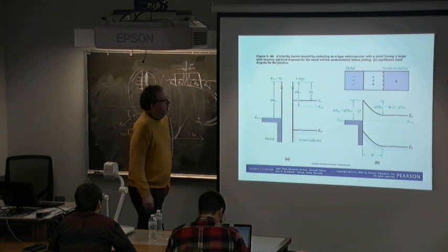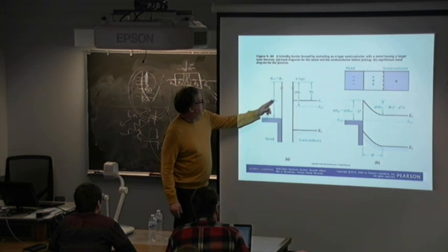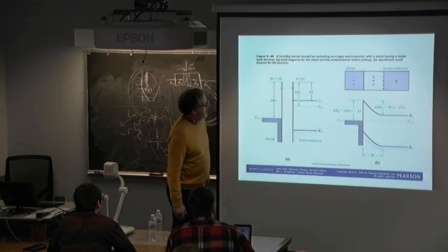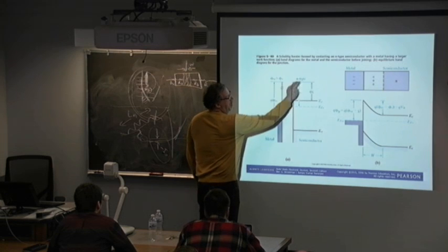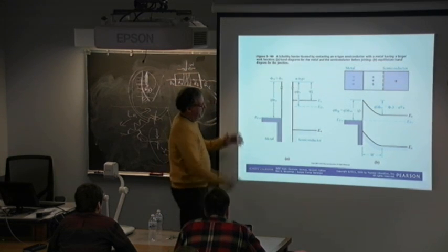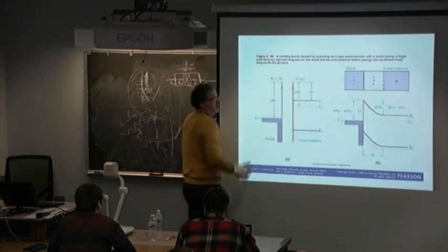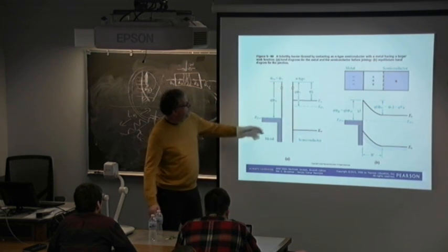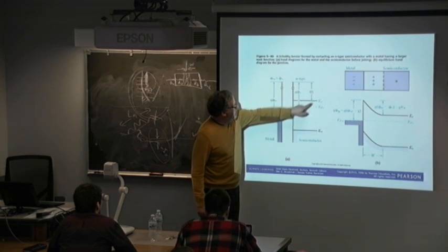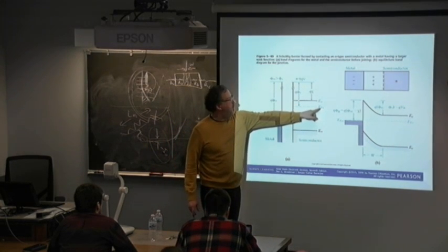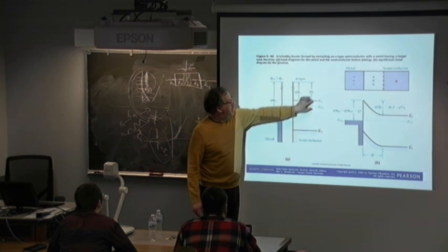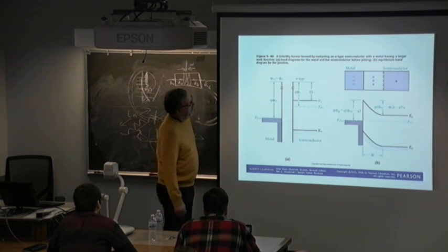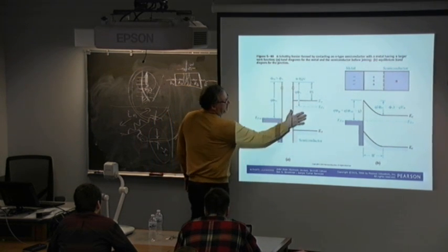So you start off with the work function for the metal, work function for the semiconductor, and then you line it all up with the vacuum level. And so this is how they align based on these. These are numbers given to you, or you experimentally determine them. And then you know where the conduction band is relative to the Fermi level because you know the doping level. So you can calculate the difference there through the equations you've been given. And so this is the metal, and this is the semiconductor.